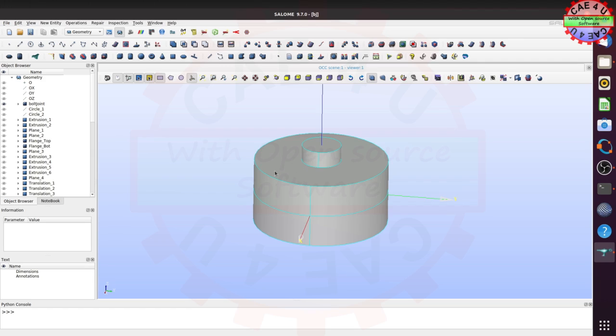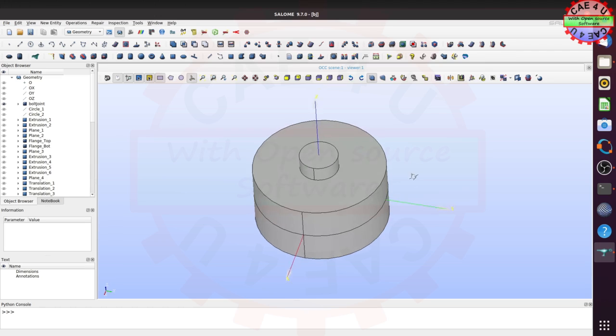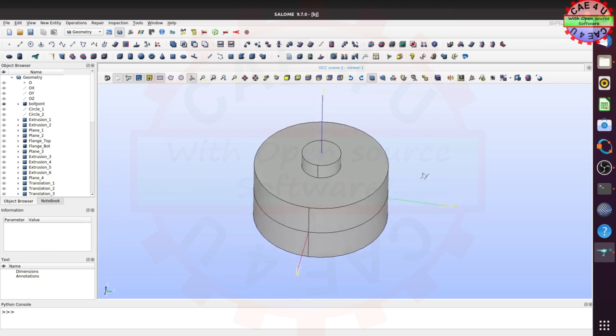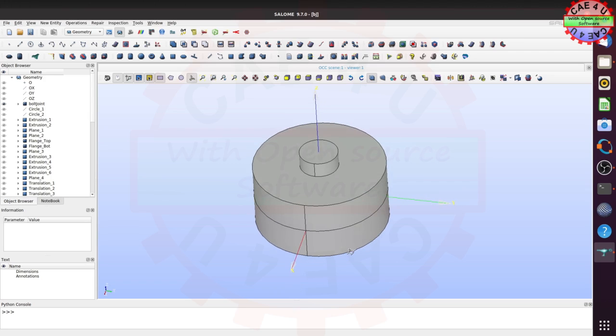Due to the length of the video, we will not go through a step-by-step explanation. However, we will focus on some of the important aspects to be taken care of while preparing the mesh. The imported geometry in Salome should be checked for dimensional consistency. Then you can scale the model as required. Here the model has been already scaled up.